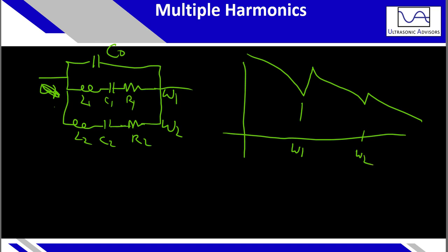As you can imagine from the simulation we did in FEA, you have an infinite amount. But however many you want to consider, you then have to adjust your static or parallel capacitance accordingly in order for all of those to sit well. Because as you pass this frequency, as you pass omega 1, this circuit starts to become high impedance. An LCR circuit has very little current at high frequency. So it practically becomes eliminated once you cross over that frequency range.